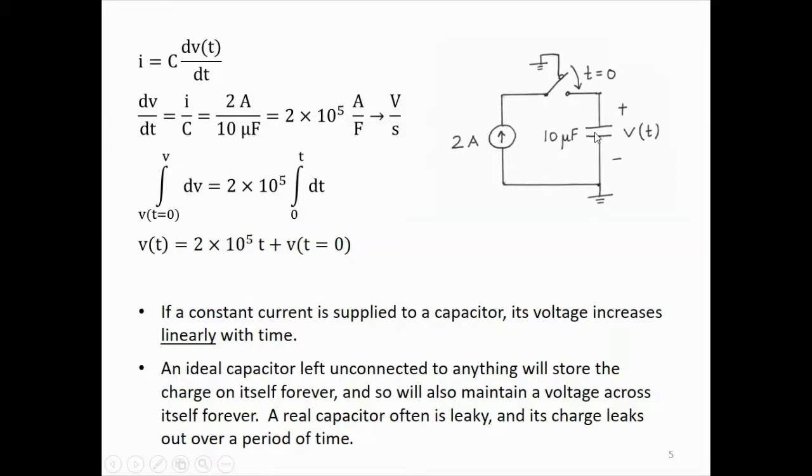The fundamental storing element in that floating gate MOSFET is a capacitor. So it is two plates separated by a dielectric, and if there is charge on that capacitor, then you say that it is storing a 1. If there is no charge on the capacitor, you say that it is storing a 0.